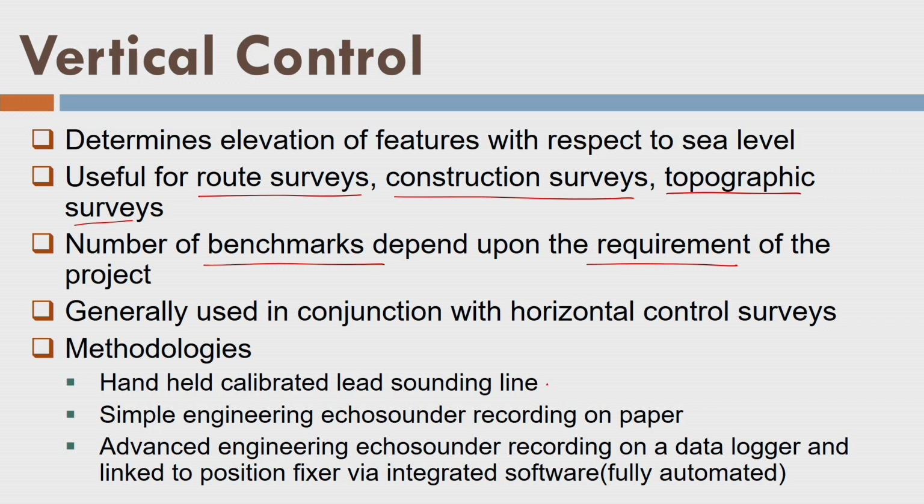So now, as we have already seen how to use the lead sounding line, and we also use the echo sounders for the depth measurement, and then we also use the advanced engineering echo sounder, that means automated systems, sometimes less automated systems. But echo sounders more or less these days are completely automated, or we say that we need minimum human intervention for the echo sounders.